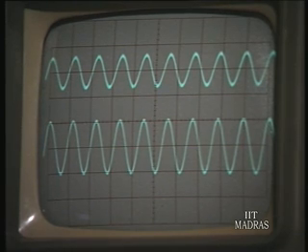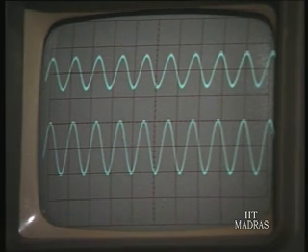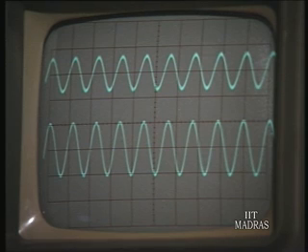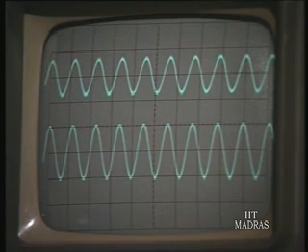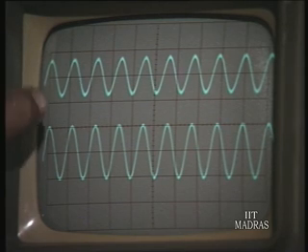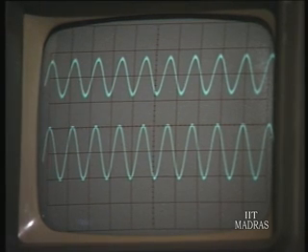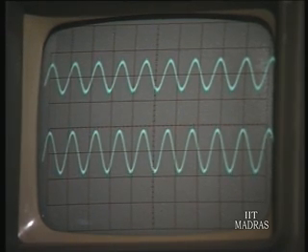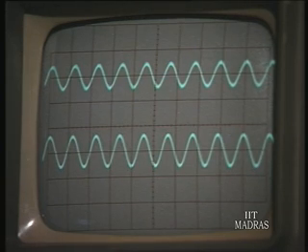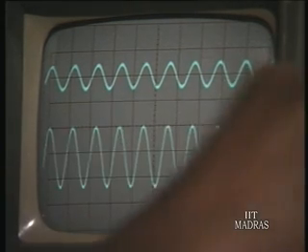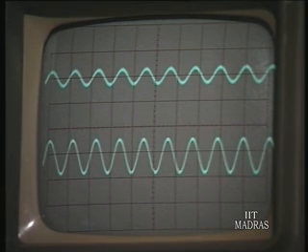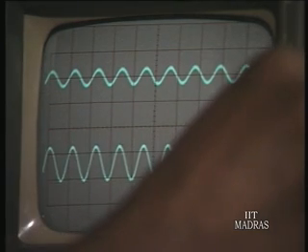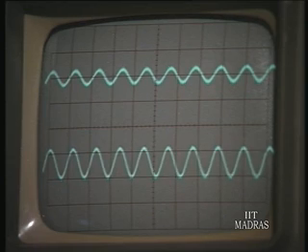Okay. Now what is the input? 4 volts peak to peak, that means 2 volts peak. Even now the output has remained constant, okay, almost, right. Now reduce, go to another scale, yeah, reduce. Now you can see some visible effect of input slowly reducing, right.